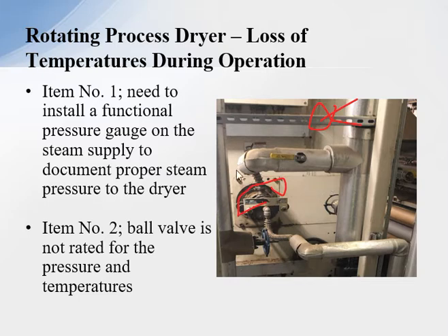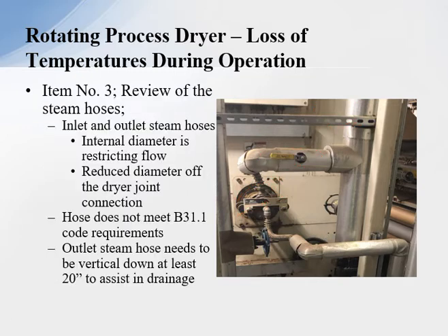The other thing is the ball valves that are installed here on the system do not meet the code compliance. They're not rated for the pressure and temperature of the operating system. Therefore, they need to be changed.